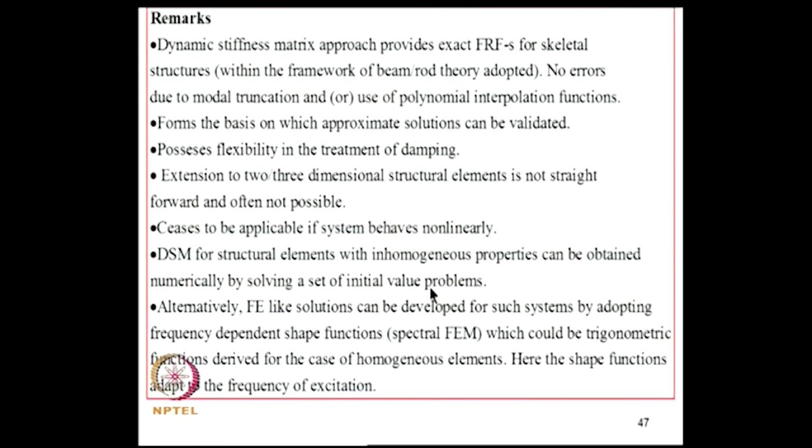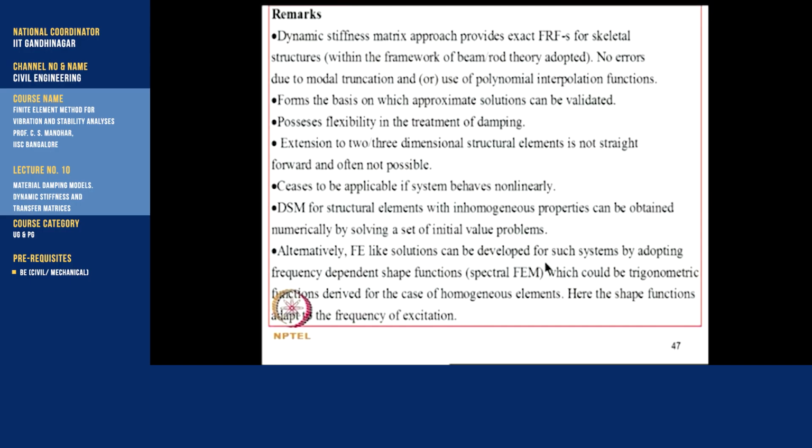After removing time, we get a special problem that can be tackled using the finite element method, but the shape functions would then be functions of lambda, which is the frequency. Such approaches are known as spectral finite element methods, where the trial functions are functions of the driving frequencies, and that helps the treatment of dynamic problems as if they are static problems.